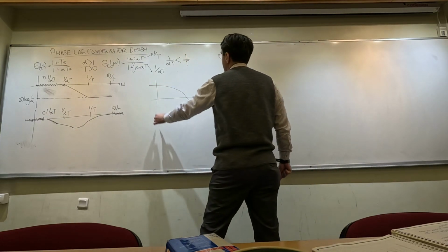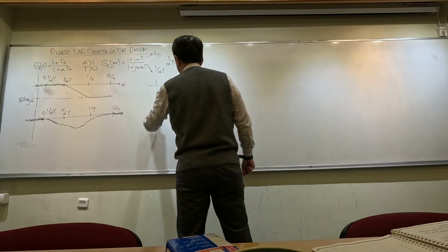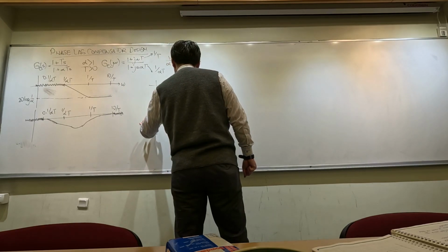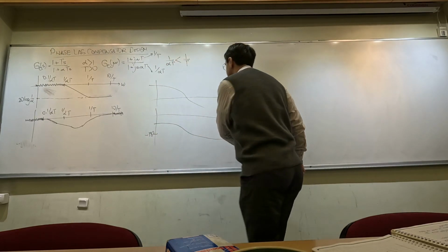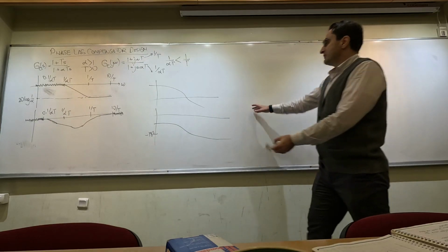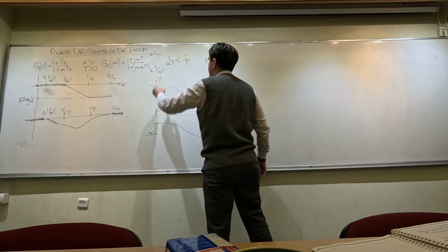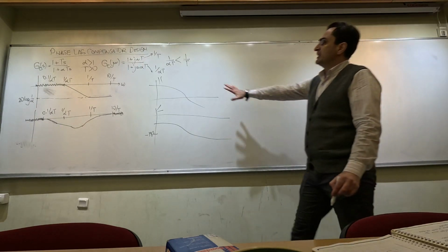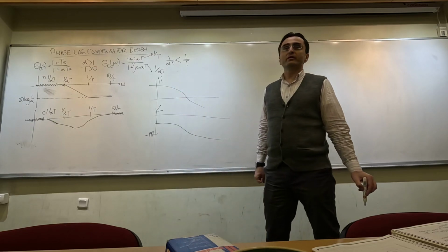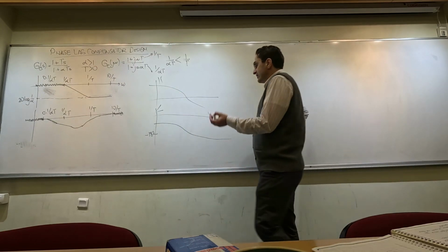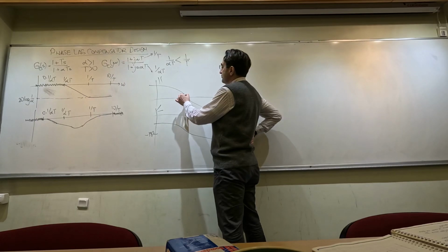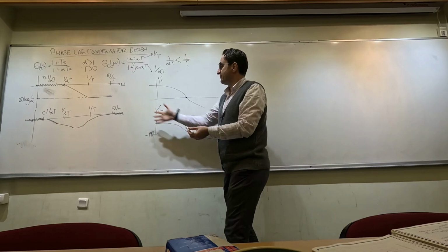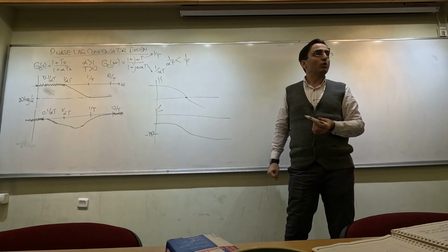So here's what we're going to do. Let's say that this is my magnitude, and let us say that this is my phase, and that is minus 180 degrees. So let me start somewhere like this. Here, this is the angle, and this is the magnitude. So for such a system, combining these two things, how can it be useful? Here is what is going to happen. When I combine these, magnitudes are going to be added, and the phases are going to be added in the open loop.